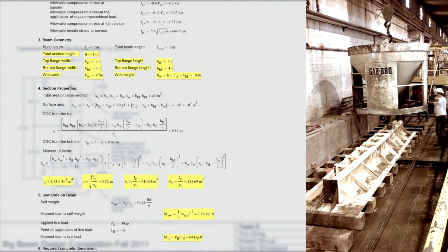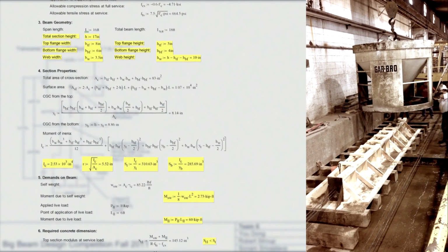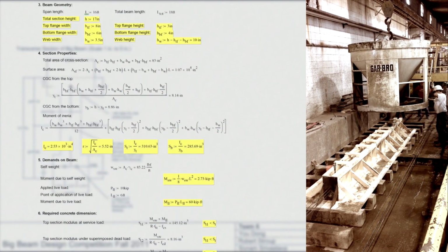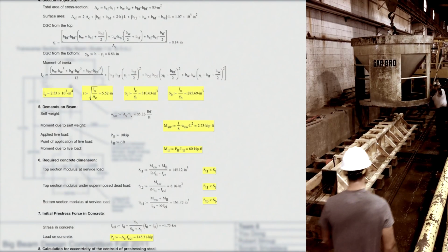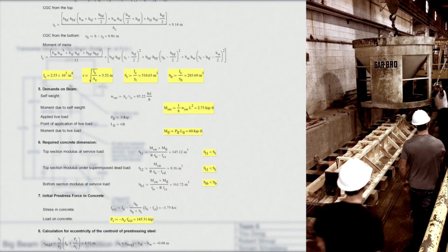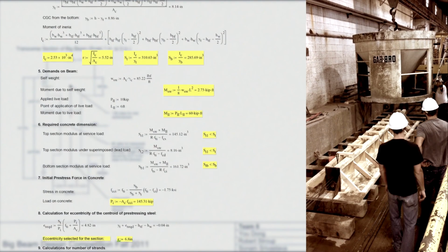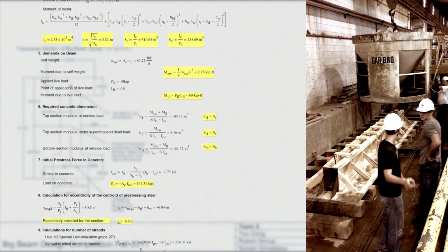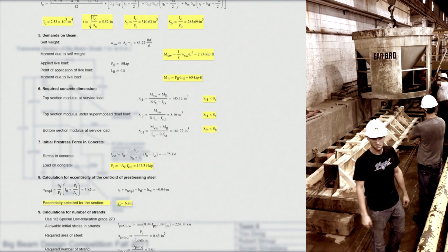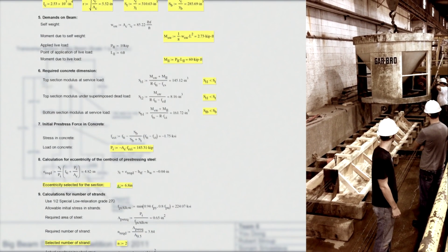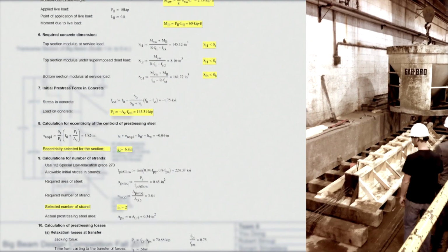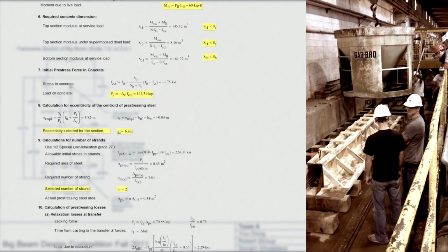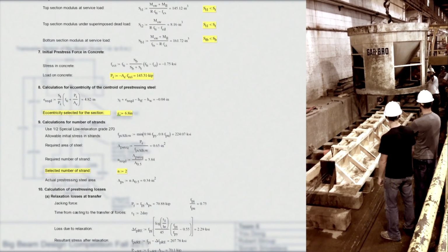For our design, the following values were given or deduced from other given values for the pre-stressing strands: elastic moduli, area, ultimate stress, yielding stress of the strands, and jacking stress. For the concrete, initial compressive stress, concrete compressive stress, unit weight, and the moduli of rupture were also tabulated. Furthermore, yield stress for A706 steel, the elastic moduli of concrete used, and the initial elastic moduli were also calculated. A reduction factor for pre-stressing losses was specified at a 5% reduction.